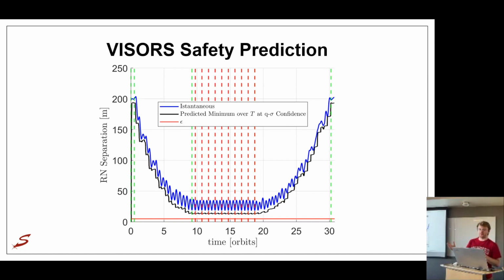So we can contrive emergencies where they are going to crash into each other because we can set the original states, but I have work to do to actually robustly test the case where control uncertainty leads to, or the thrusters fail, stay open, and lead to huge degradation of the relative state inclination vector separation, and how that affects these solutions. But that is the methodology behind these systems of VISORS and what they will do to protect us and make us flight capable. That is all.